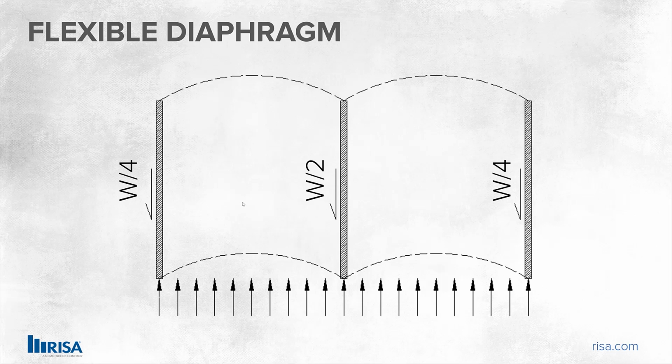So one thing to think about when you're using flexible diaphragms is that a flexible diaphragm, because in our case it has zero stiffness, is not going to provide any rigidity to the top of a wall, say. So when you're using a wood wall, they may have the tendency to simply fall over due to the minimal stiffness in the wall and no stiffness at that top diaphragm. So that's why adding things like straps to tie the walls together at the floor levels is so important.